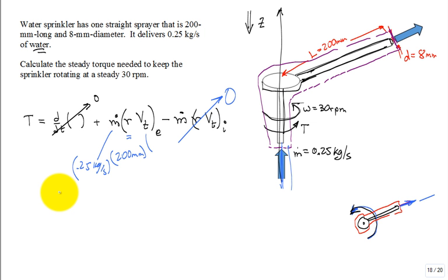That's exactly right. So if you looked at it, the little chunk of fluid, when it leaves this tip, yes, it's coming out relative to the tip with that speed. But the tip is also moving in that direction. So the velocity of the fluid leaving the tip, you have to add them both up, and that's its total speed. It's shooting straight out, but the tip is also rotating, so I have a rotational component, and the net speed is at an angle, not straight out. Okay?